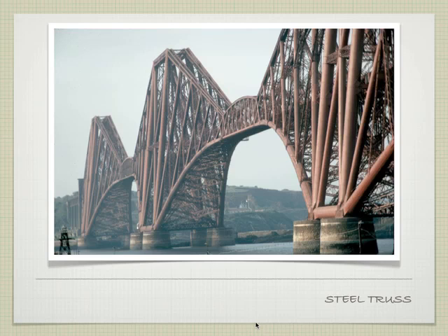It depends a bit on the steel that goes to make up this, right? Typically, and this is one of those, there's always these trade-offs. For its weight, this is significantly stronger, right? But that's not to say that if we had two that were exactly the same depth, the plate girder wouldn't be stronger. Does that make sense? But it weighs significantly more.